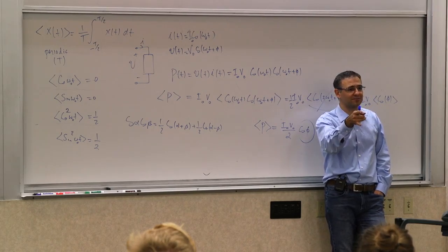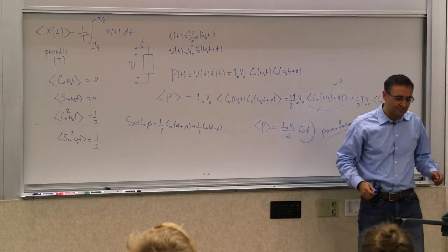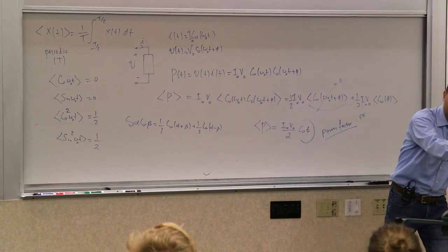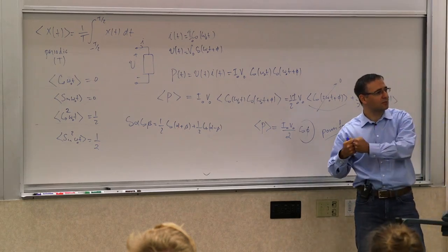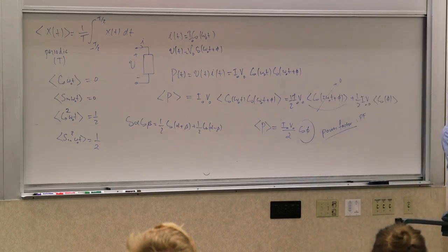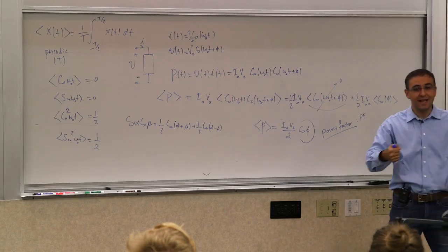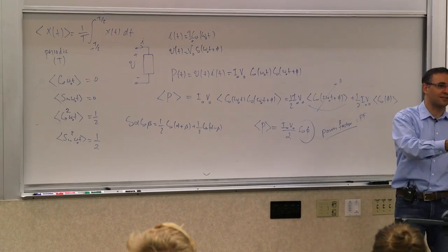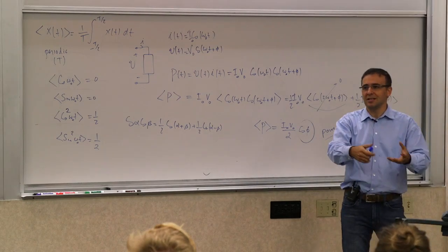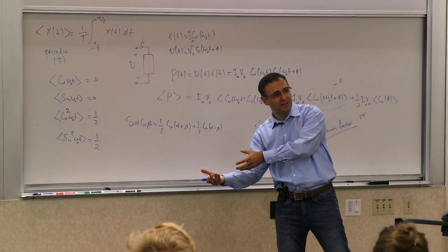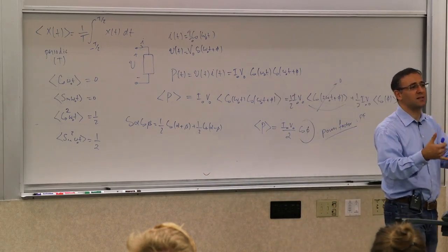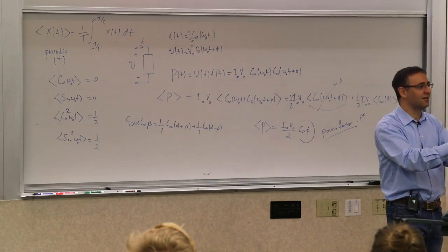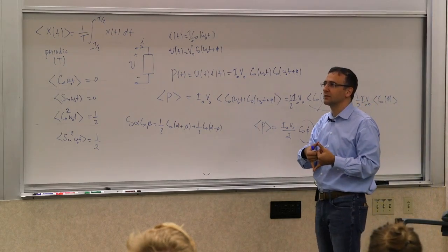and it cancels it. So what's really happening is that when there's this power exchange within a cycle, right? You remember, for a little bit of it, it takes power, and then for the other part of it, it returns the power. What happens in this cycle? The motor still does that, but instead of with the network, it does it with a capacitor. So for the period of time that it needs the power, the capacitor is the one that's providing it, and vice versa. And that's achieved by setting its susceptance to be exactly the same magnitude and opposite sign, opposite polarity of the network.